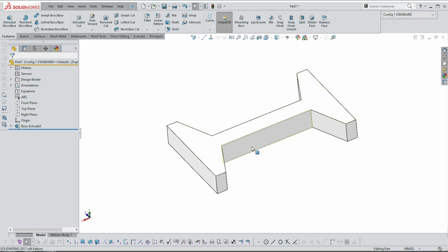Right, so I want to cut a shape out of either side, and then I want to add maybe some other items. So let's just go to the top plane. I like to use these 3 planes. That's because I like to keep this design tree as simple and as usable as possible. If I keep adding planes in, it becomes difficult to find things. And I can do just about everything I want to from these planes. I don't have to stick to the planes as a starting point.